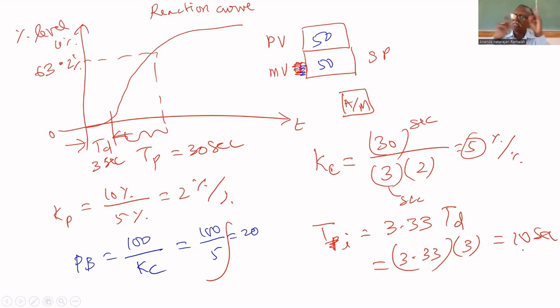Set point equal to PV, yes. You adjusted the set point. When it displays set point, you can adjust it, increase or decrease. If you press enter, the set point will be accepted. So you made set point equal to PV, and the process is at steady state.